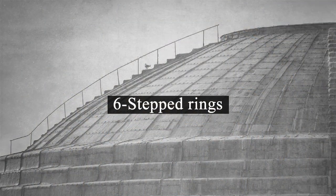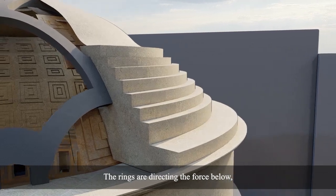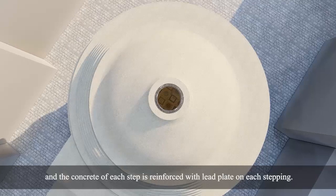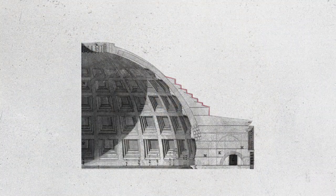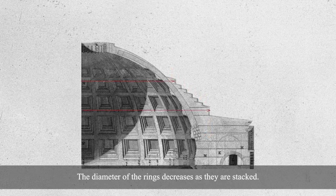The sixth element is the stepped rings. The rings are directing the force below, and the concrete of each step is reinforced with lead plate on each stepping. Each ring is stacked on top of each other. The end of the upper ring starts at the center of the ring below, allowing the weight to be uniformly distributed across the concrete and eventually down to the wall below. The diameter of the rings decreases as they are stacked.